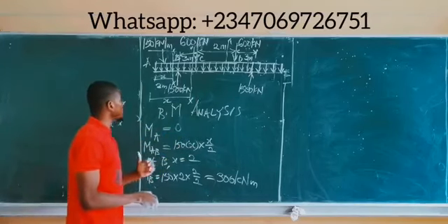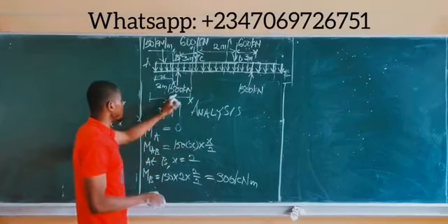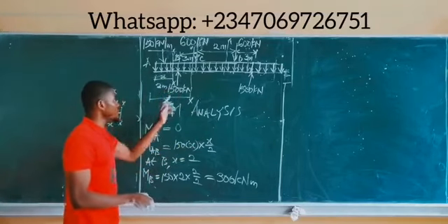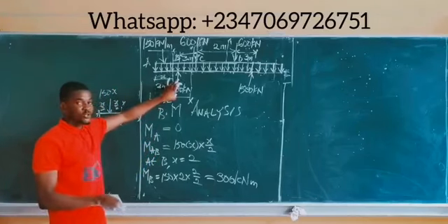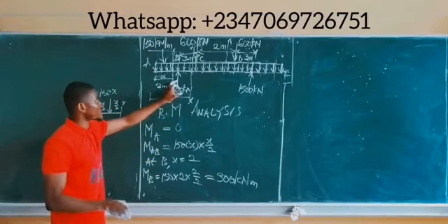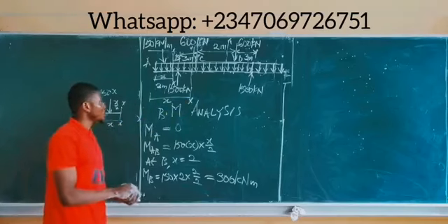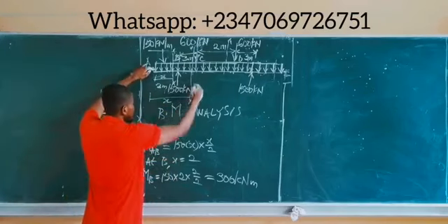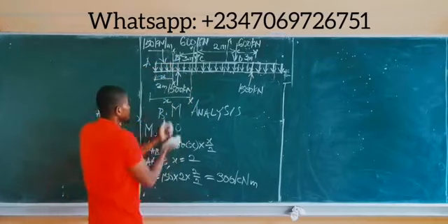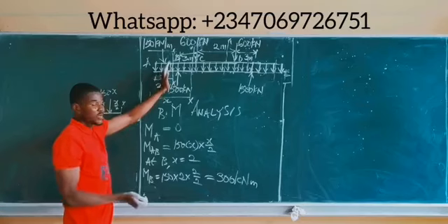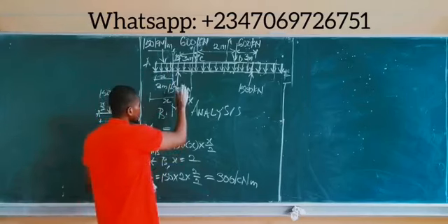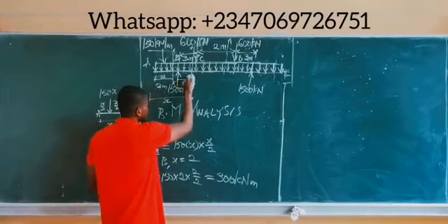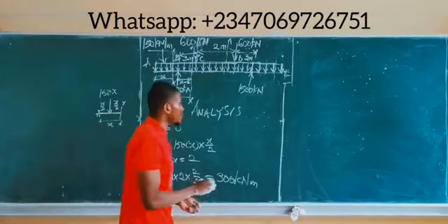That's the first thing. Secondly, I now have a force of 1,500 pointing upwards at point B. It is this force that I will have to find the length for, because this is just a point load, it's not a UDL. So I need to find the length of this force about the point of section. As usual, if from A to the point of section is x, what is now from B to the point of section? Simply remove the length that we don't need out of it. Our length there simply was 2 meters. So therefore the length of this force, 1,500, about the point of section is simply x minus 2.